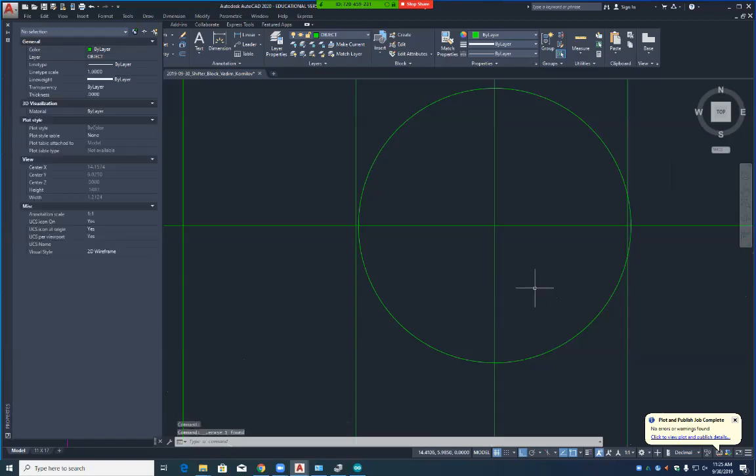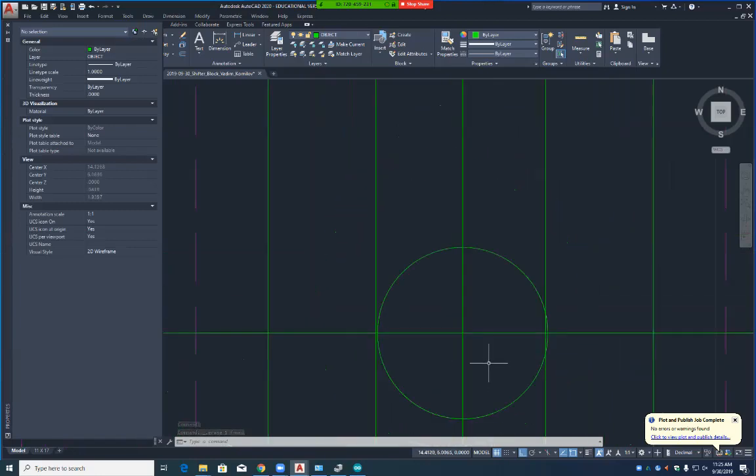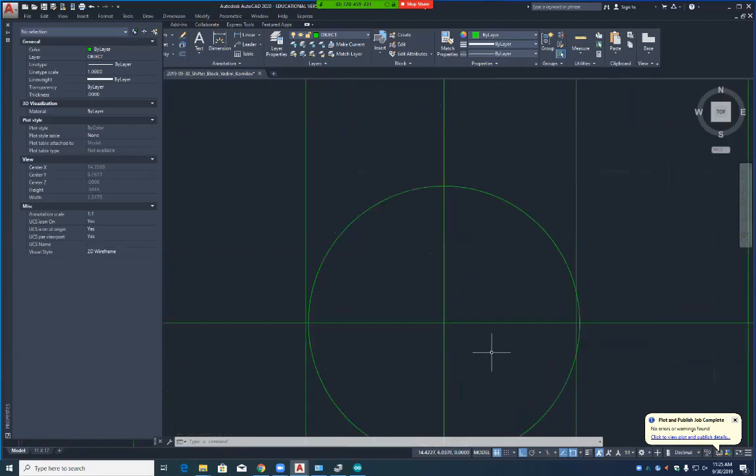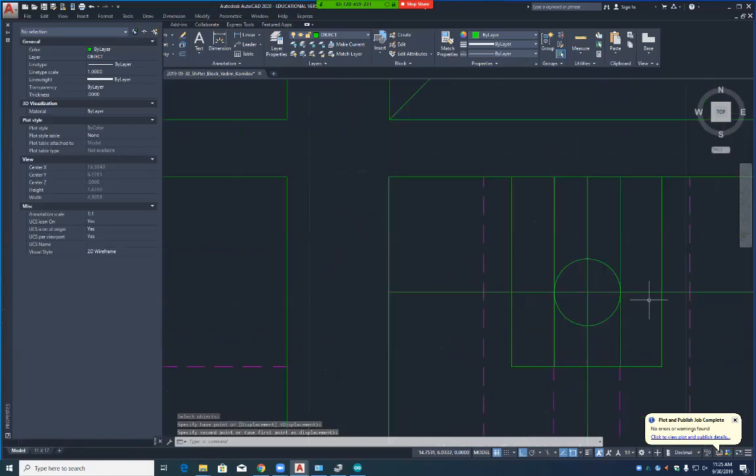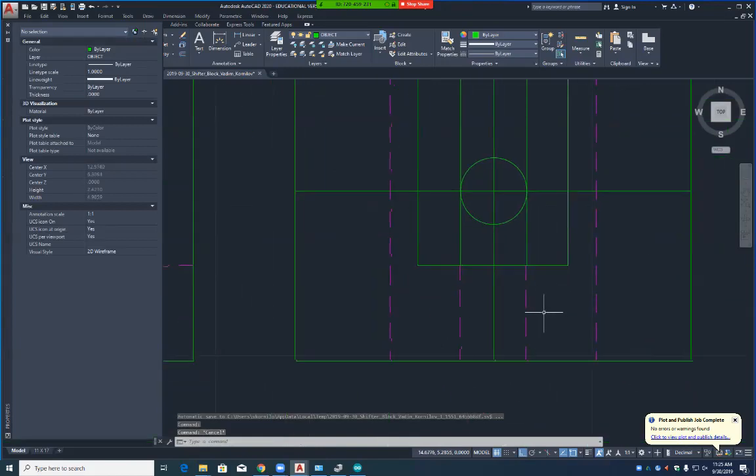Wait, so they would be solid. Yes. So it would be like this here, basically. That one, and that one, and that one. But we're doing a section view though. Exactly. That's how it'd look if you were doing the traditional front, top, right side view. Okay? That makes sense? And then we wouldn't draw the hidden line behind that exact line anyways, because an object line is more powerful than a hidden line. Okay, but now we're going to make this into a section view drawing.